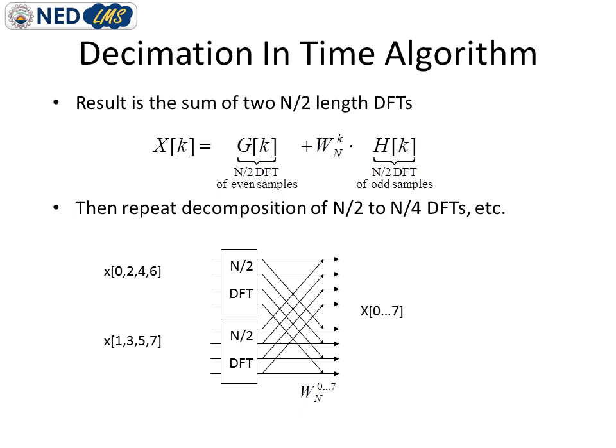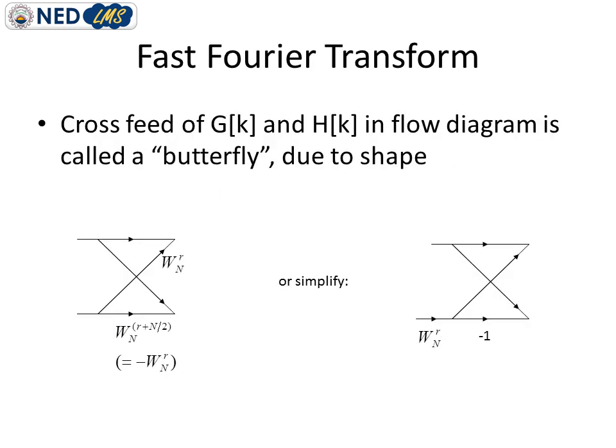So we have to apply some mathematical operation at each and every step. If you zoom in on that butterfly structure I told you about in the previous slide, each of these lines is multiplied with a factor W_N, and for the diagonal lines its value is equal to 1, and for the straight lines, or lines with angle 0 degrees, it is multiplied with this factor, and if you calculate this factor it comes out as -1, as simplified in this figure.